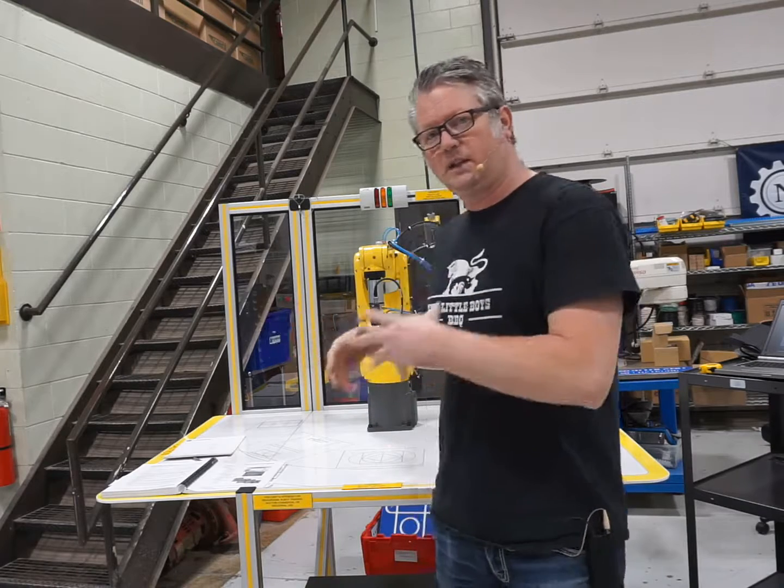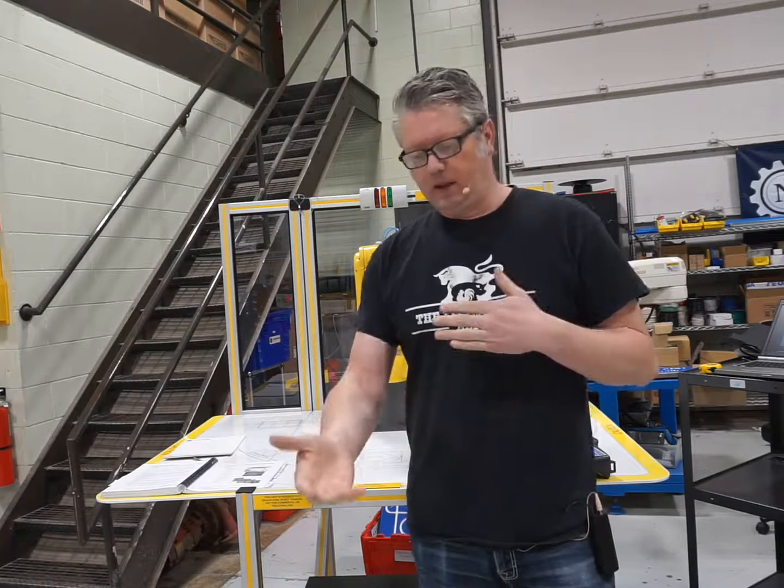So the robot is typically used in conjunction with another controller, a PLC, and the inputs and outputs are being fed either directly from the robot to the PLC through hardwired connections, or they are done with Ethernet and communications through digital means, like Modbus, CAN bus, Profinet, some sort of digital communication standards.